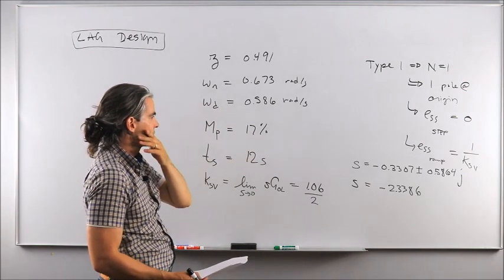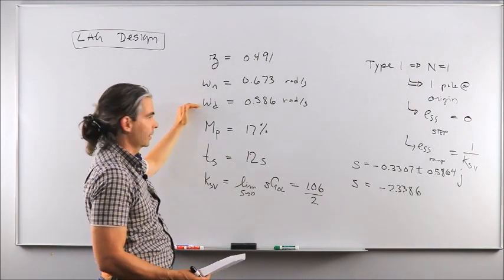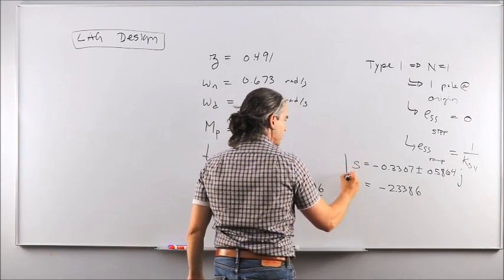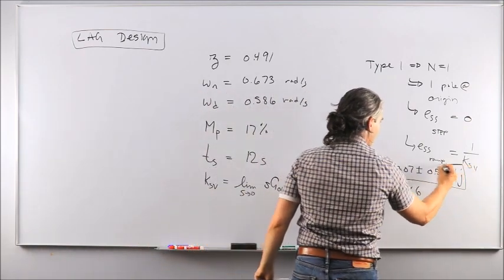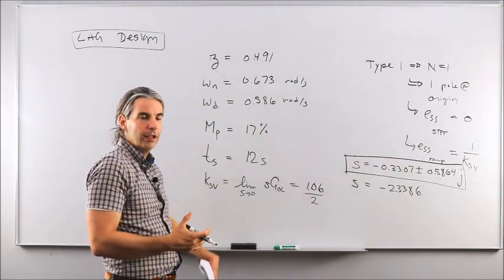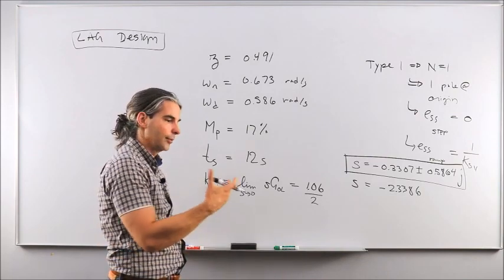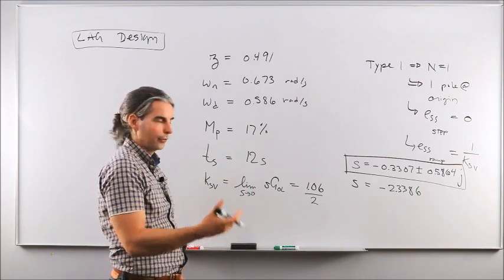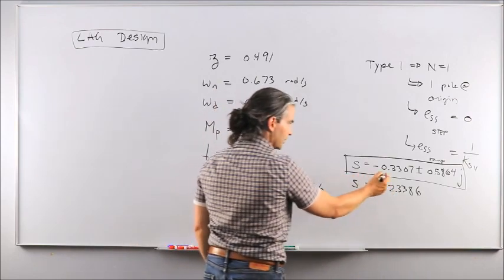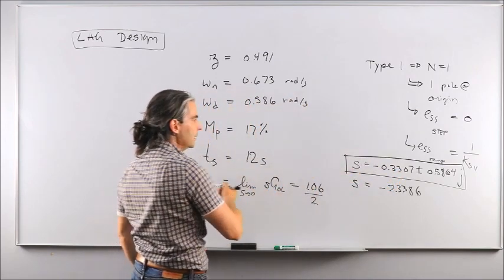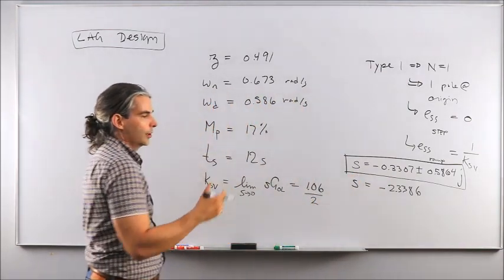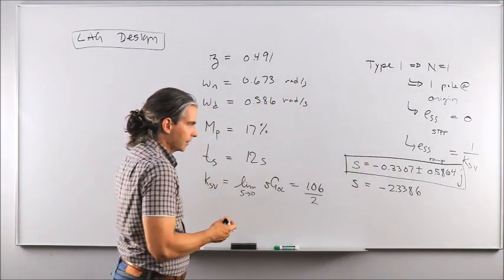So how can you go from 3 poles to one set of characteristics? It's because you need to do the calculations for what's known as the dominant poles. The dominant ones are the ones closer to the imaginary axis, and those will have a greater impact overall on the time domain performance of your closed system. That other one, almost 10 times further left in the complex plane, is not the dominant pole, so its influence on the transient performance won't have a great impact.